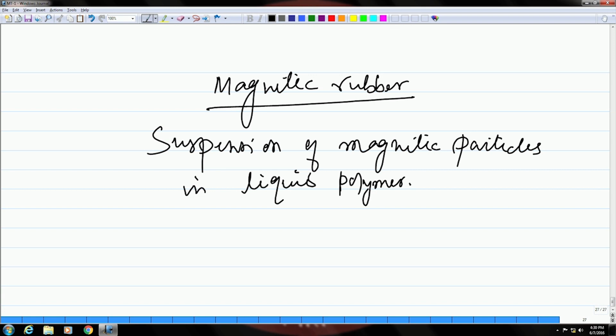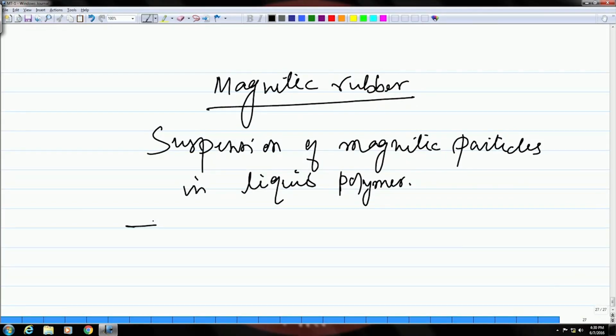So, this has a liquid polymer which contains the magnetic particles in suspension. Now, this liquid polymer you can apply on the part, on the inner diameter, for example, that you are going to examine, and allow some time for this liquid polymer to cure or to set. So, unset polymer which contains the magnetic particles, you apply it first on the part.